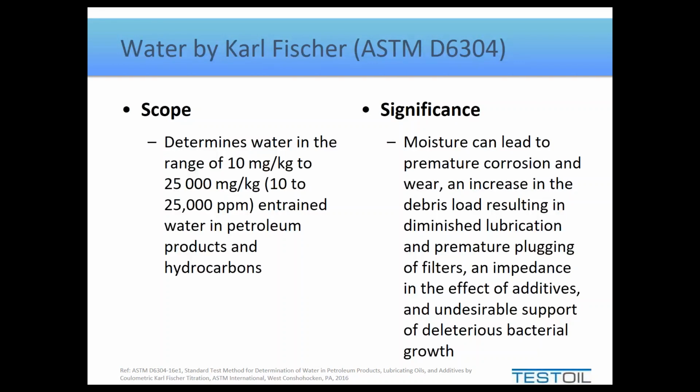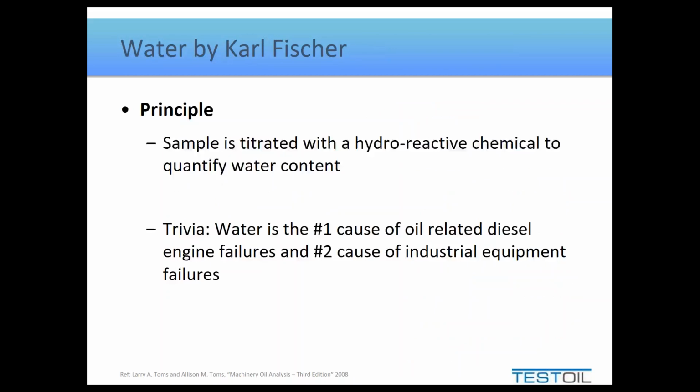The significance of measuring and quantifying water is understanding if the water contamination is actually getting worse, if we should expect more contamination showing up on particle counts, if we should expect more oxidation of metals, and so forth. Now, the basic principle of the Karl-Fischer is that it is a titration. If you remember your high school chemistry, it is a reaction where you're basically trying to neutralize an acid with a base, which would be a common titration that you would have done.